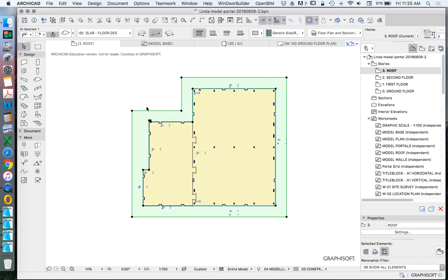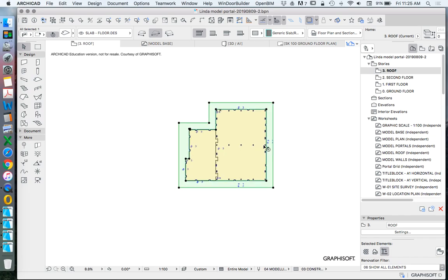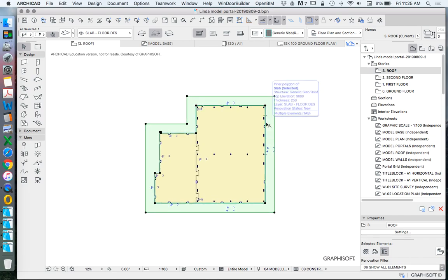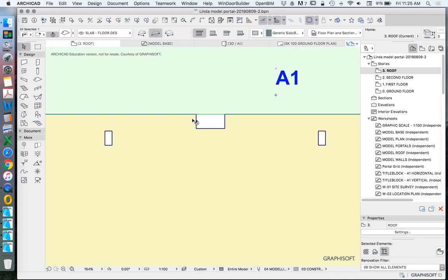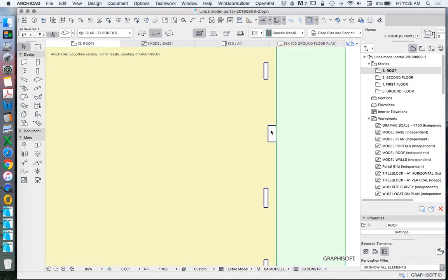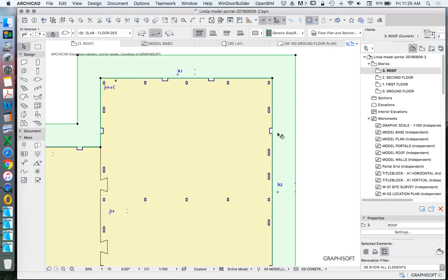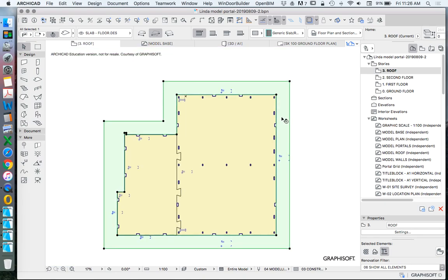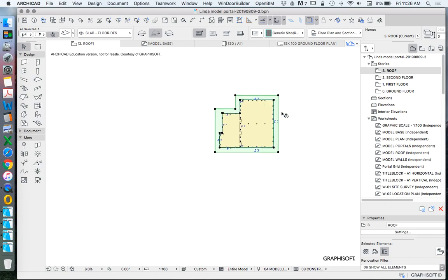And then we've got another slab around the outside, and this is sort of to create a bounding box, which will sort of lock it all in, but it's also intended to be slightly lower than our floor, so it looks like we've got a slight rebate, which happens in real life, but it also will lock in all of these edges, and so the feet of the walls would otherwise fall out the sides without something around the outside of them. So it'll help for that as well.